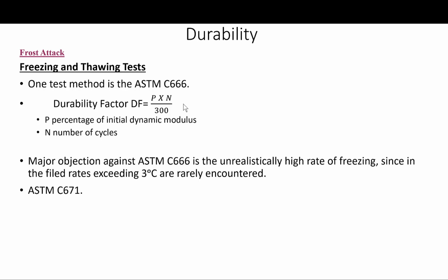Okay, both procedures A and B are used by various agencies to evaluate the durability of coarse aggregate, as well as the durability of concrete mixtures as a whole. So that's another thing. Procedure A is especially severe since most specimens eventually become fully saturated and eventually fail. So even concretes that perform well in the field may perform poorly when subjected to cycles of freezing and thawing in water. And again, we need to replicate the conditions and be accurate in our predictions of the service conditions of the concrete in order to run the test. Otherwise, the test will not be representative of what will happen, or vice versa.